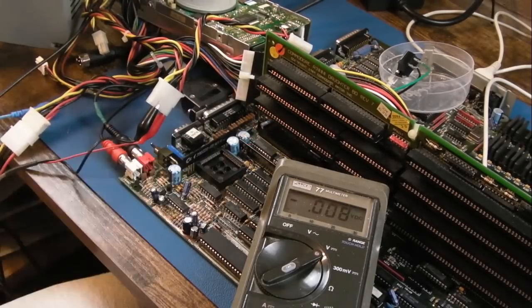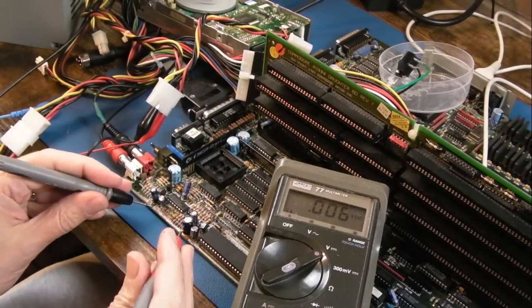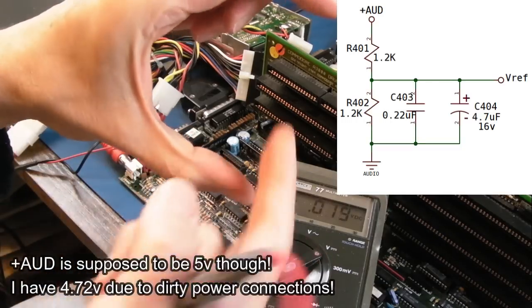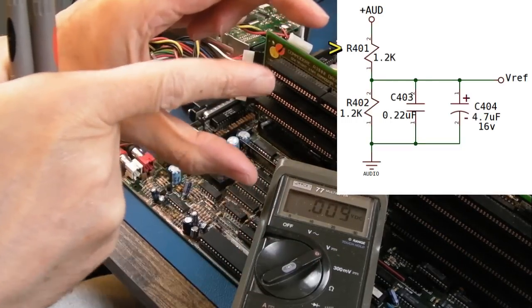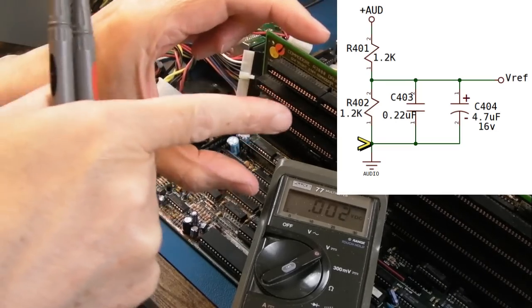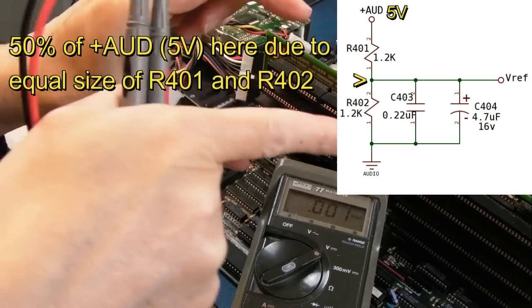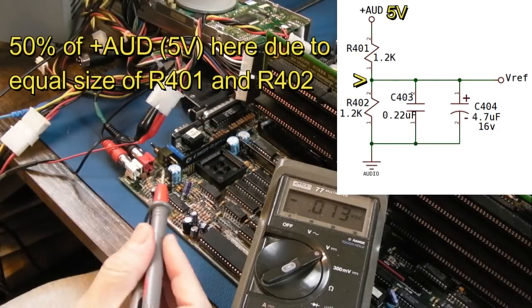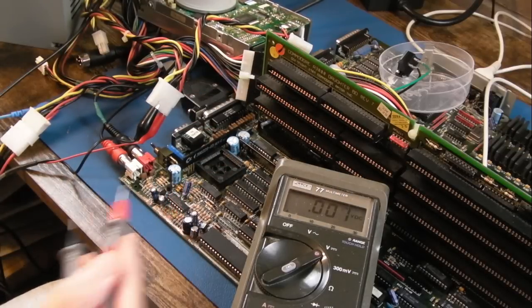It was a bit under, as I say, it was like 4.7. In fact, I could show you that as well if I measure the bottom side of this resistor here. 4.72. So you've got a potential divider, 1K2 and a 1K2 between 4.7 volts and 0 volts, and because they're the same size resistor, you get a 50% reduction in voltage through that potential divider. So that's what provides the VREF.